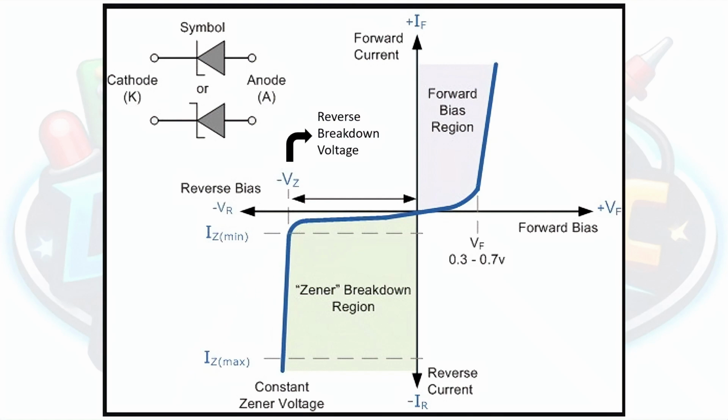However, when the voltage on the Zener diode exceeds that reverse breakdown voltage, it is now operating like a voltage regulator. To further understand that, let's take a look at this shaded area I marked here. As you can see in that shaded area, even if the current goes up rapidly, which normally happens when there are voltage fluctuations at the source input or the input voltage, the voltage across the diode remains stable.